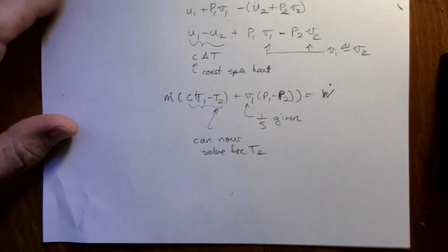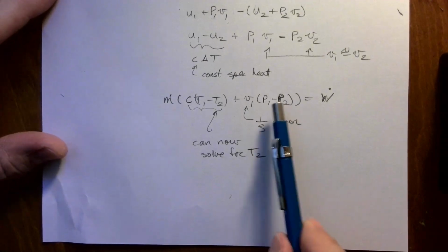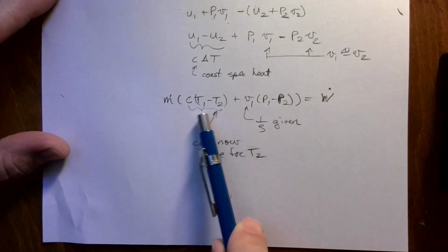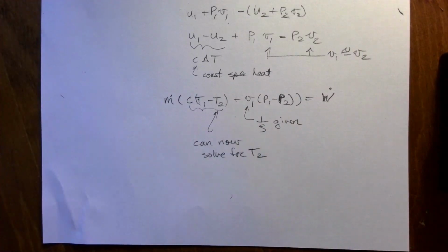There's another problem that involves, I think, a passive water heater that has liquid water coming in and liquid water going out. So ultimately, you're going to have an H1 minus H2 evaluation in that as well. So it'll be similar in that you'll need to include the internal energy plus the PV term as well.